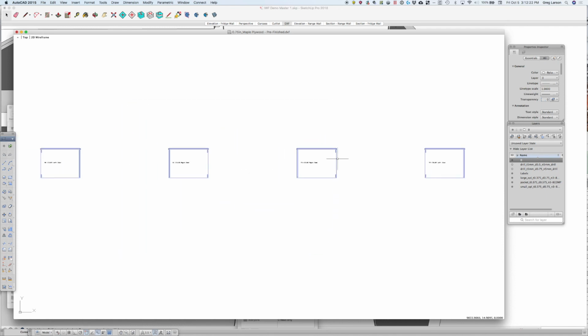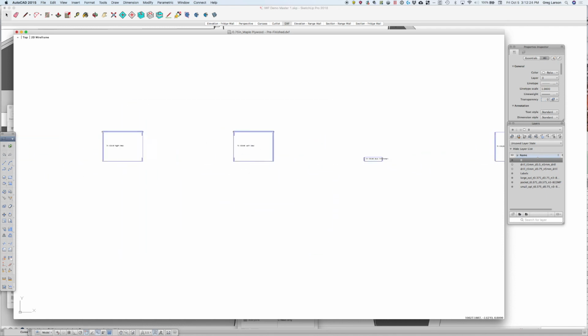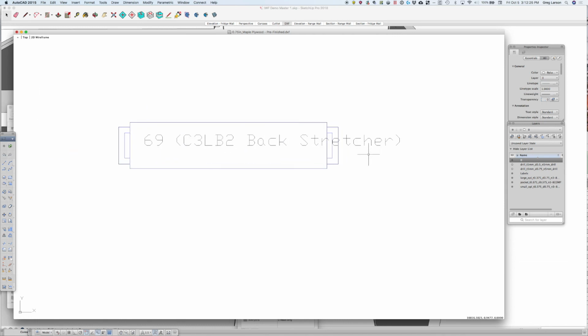If we look at one that's got some tongues, we'll see here that if we turn our pocket layer off, you see how it's overcutting on the ends and all the way around so that we avoid having little bits of material still there with the radius. If we stopped just within this boundary of this tongue, we would have little radius parts that weren't cut there. So you can see the pocket overcuts.